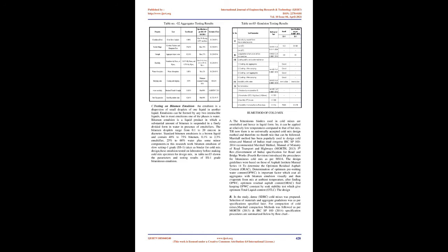1. Impact value. 2. Water absorption and specific gravity. 3. Durability by soundness. 4. Sand equivalent value, only for fine aggregate. 5. Combined flakiness and elongation. Coating test was conducted of water emulsion mixture with aggregates including filler to determine coating ability of aggregates visually. Table No. 02 shows the result of aggregates testing and their specifications.